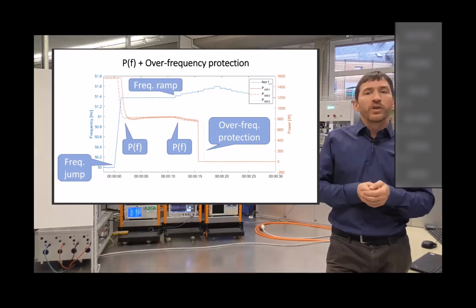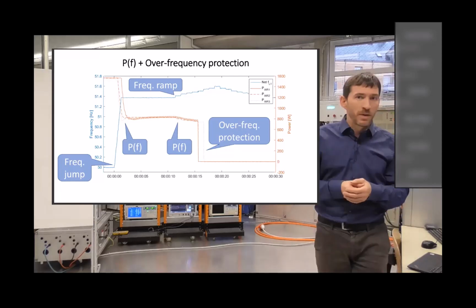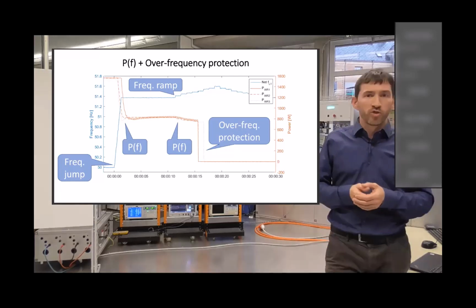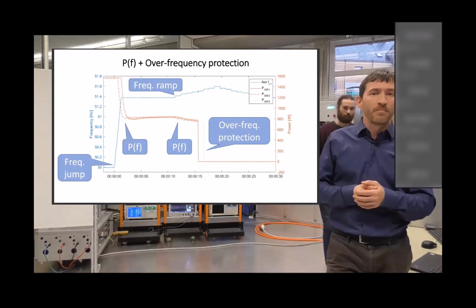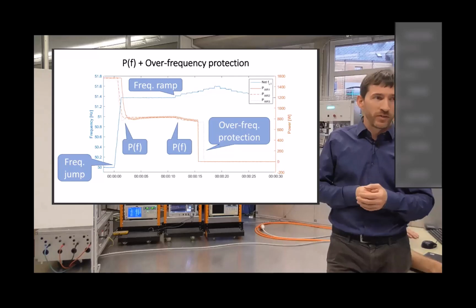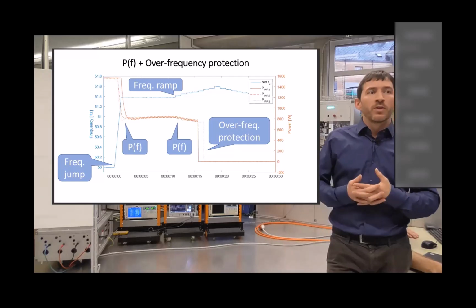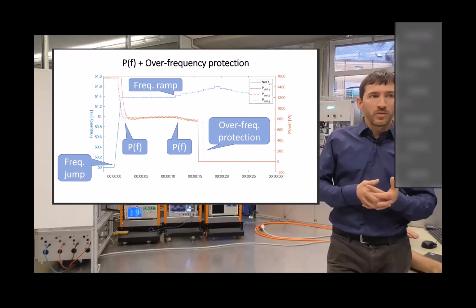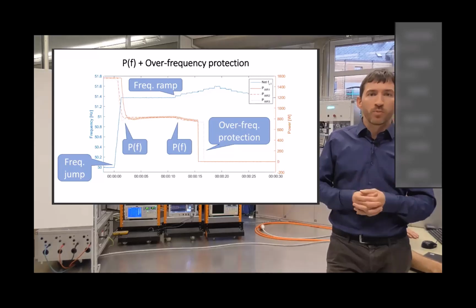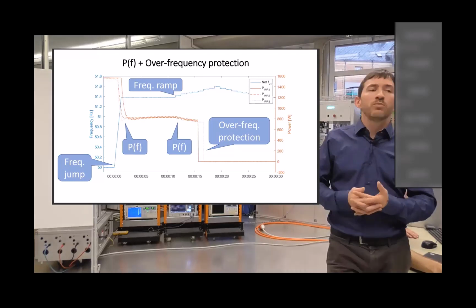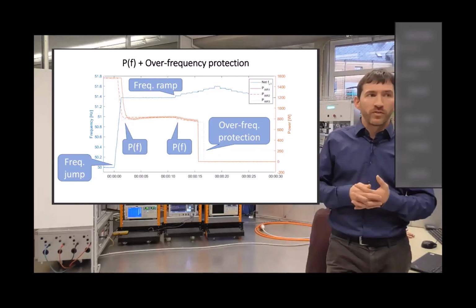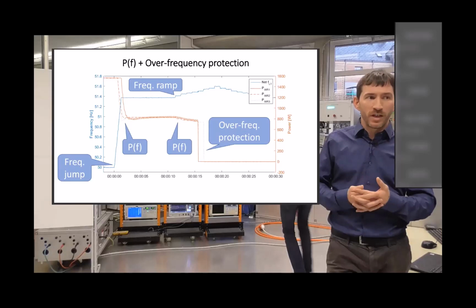So if you look at the graph here, I try to explain this graph, what should have happened, what has happened. Hopefully it's, or now I can say it's more or less the same. So these inverters have passed the test. When we start this frequency watt control and our frequency protection, what actually happens, or what we emulate, is we assume that the frequency first is at 50 Hertz. That's what you can see on the very left of this graph.